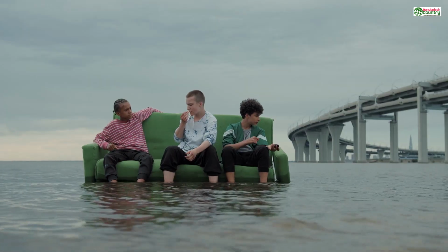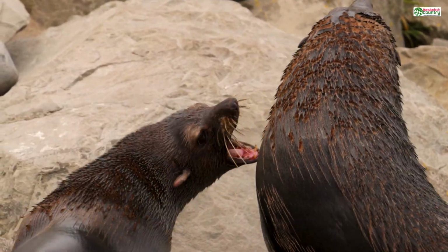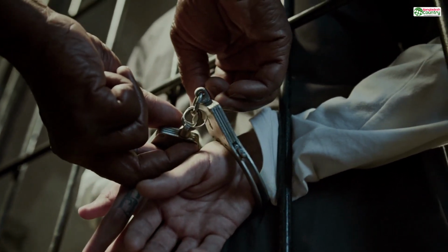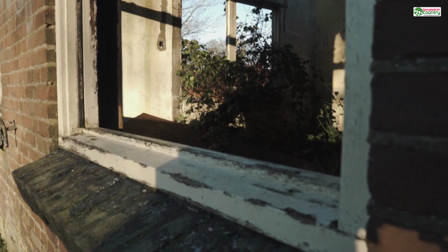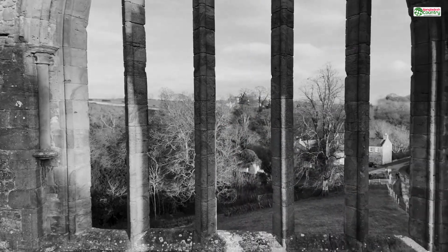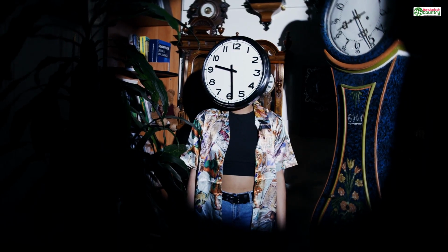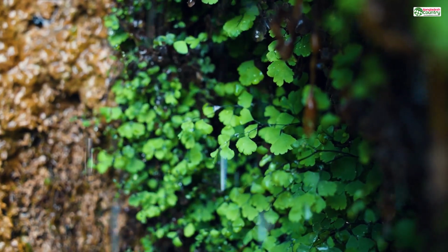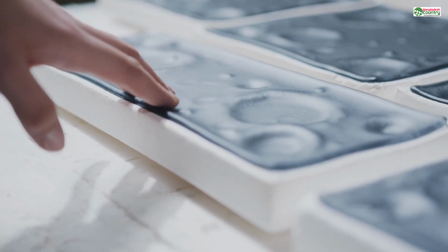But if you send this sealed file for a resin print, the consequences are far worse. The inside of your model will be filled with uncured, liquid resin. It's trapped. The service will wash the outside, but the inside remains a toxic liquid slush. Over time, that resin will find a way out. It will seep through microscopic pores in the print wall, making the surface sticky and dangerous to handle. Worse, gases can build up inside from the slow curing of this trapped resin, and the pressure can literally crack your model open from the inside out days or weeks later. It's a messy, toxic, and heartbreaking failure. This is the number one mistake I see.